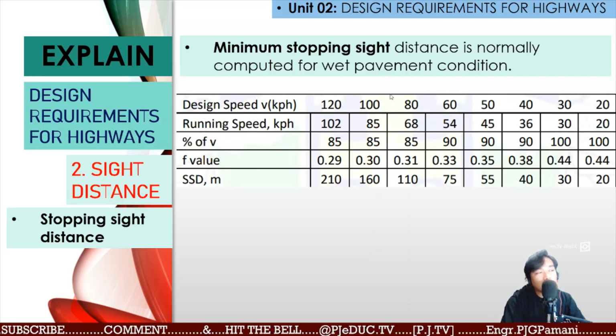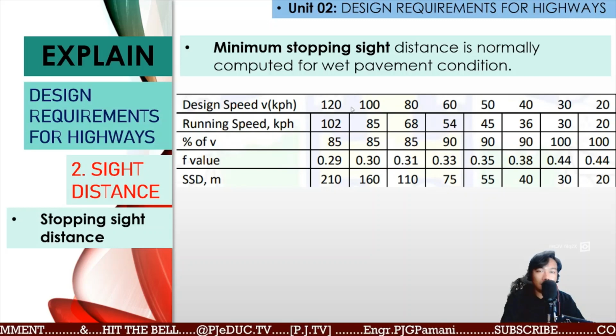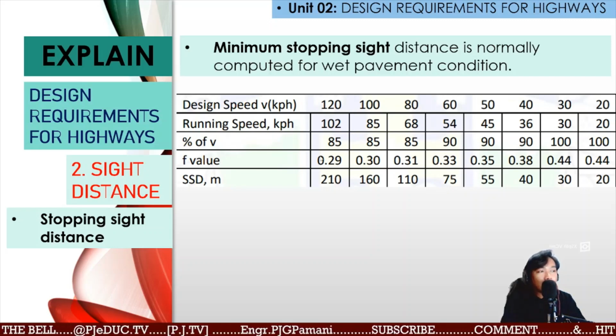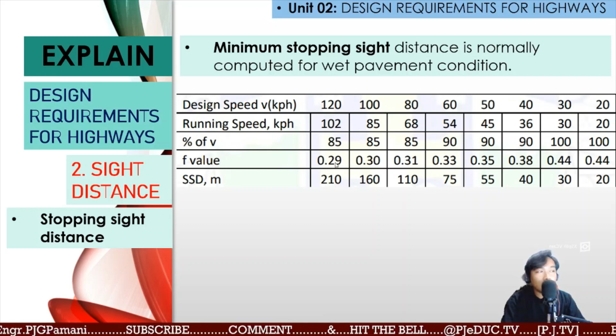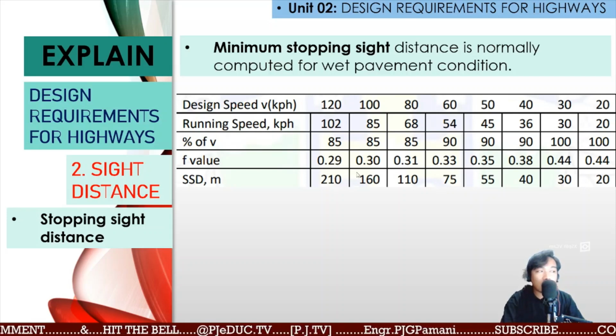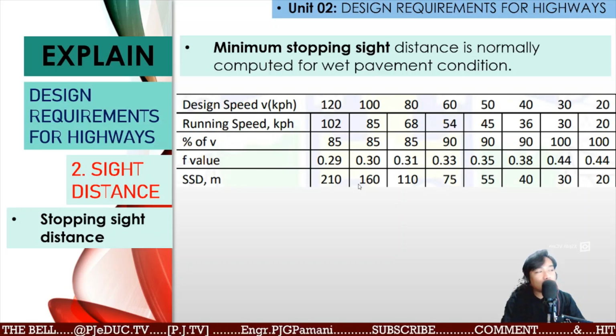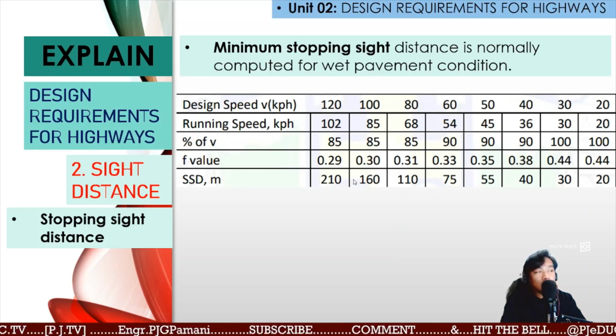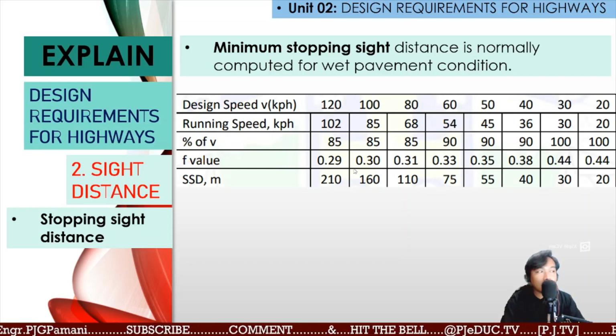So for example, we got a design speed of 110, no? The velocity came out at 85 also. 85, 110, then 29. Then friction is at a minimum of 0.29, but what we used was 0.30. And we have computed that it is 175. So 175, so we should make that exact, we change the friction, change the velocity, change the actual speed, and at a distance of 210. So this will now be the new value and our reference design values.